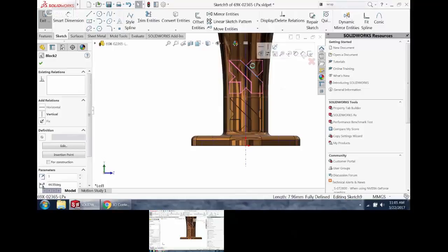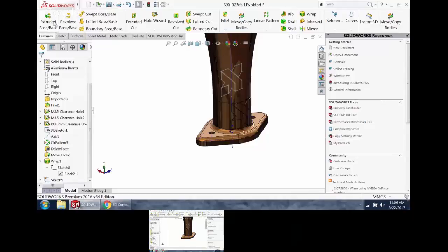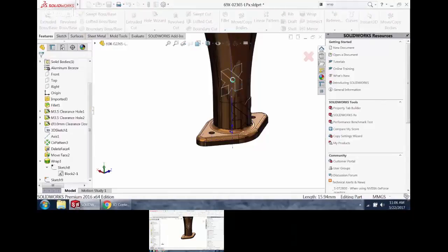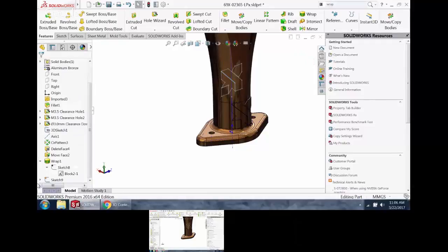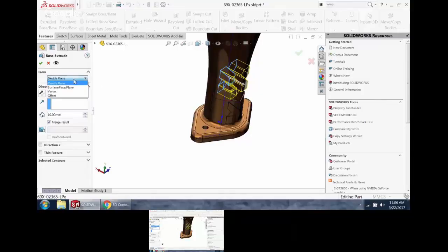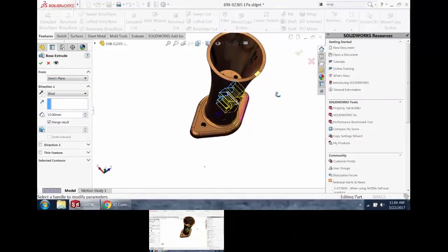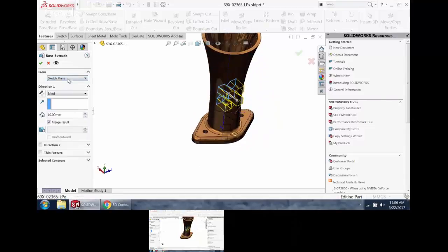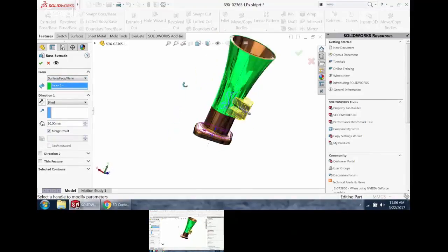There's a couple different ways I can do this. It depends on what I want for the end geometry. I can do it as an extrusion, where I pick the entire sketch, extrude that by, instead of extruding from the middle of it, which would be bad since this thing's supposed to be an air intake and it would fill it up with metal, instead of extruding from the sketch plane, I can extrude it from a surface and start it extruding from there. Leaves the thing hollow.